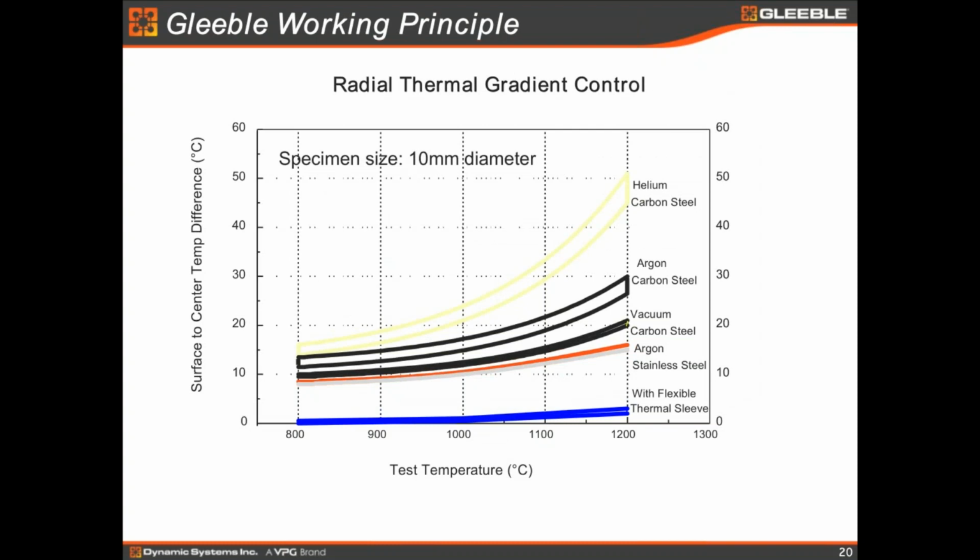Another thermal gradient, which is very important too, is the thermal gradient along the radial direction. Lots of people probably know already that in ingot casting, we will see some holes in the center of the ingot. Lots of people probably know already why. Because the shell solidifies first, right? And the center solidifies the latest.